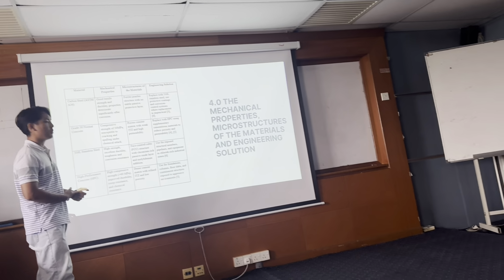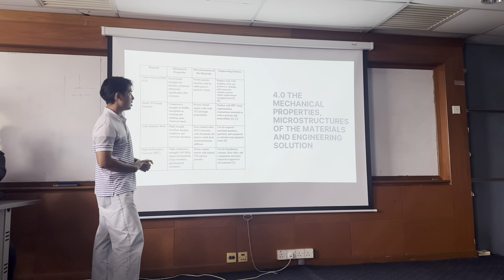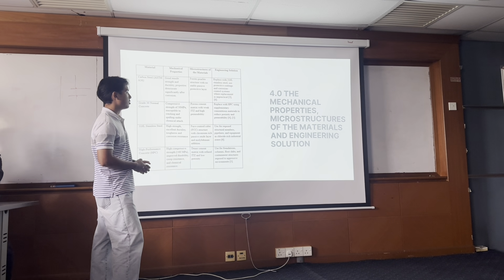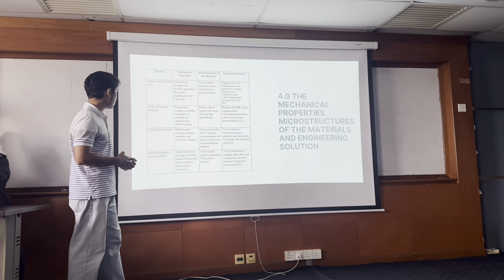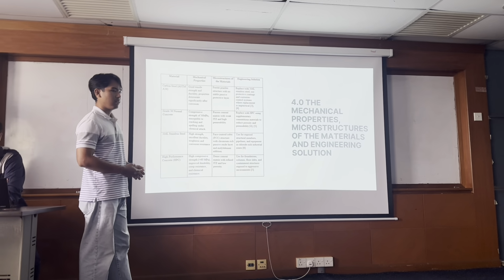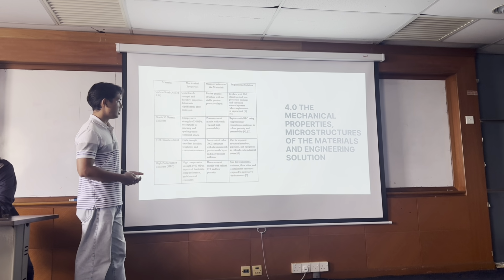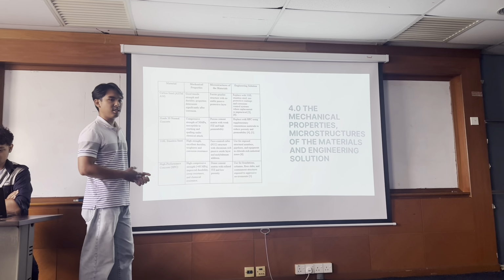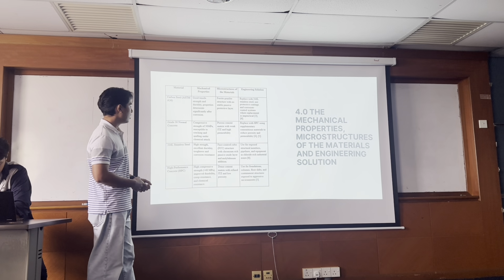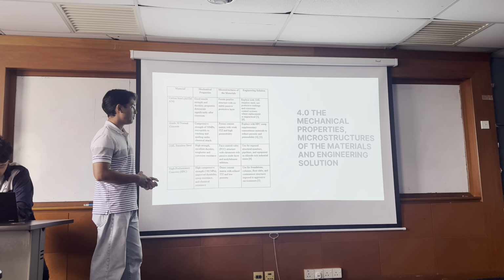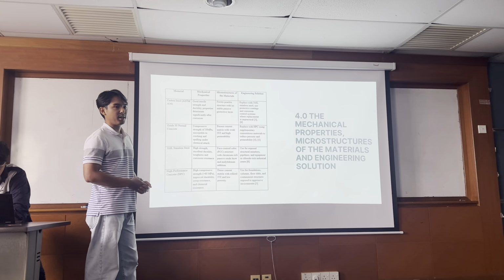The grade 30 normal concrete must be replaced with HPC using supplementary cementitious materials to reduce porosity and also the permeability. The 316L stainless steel is used for exposed structural members, pipelines, and also equipment in chloride-rich industrial zones. The high performance concrete, HPC, is used for foundations, columns, floor slabs, and containment structures exposed to aggressive environments.